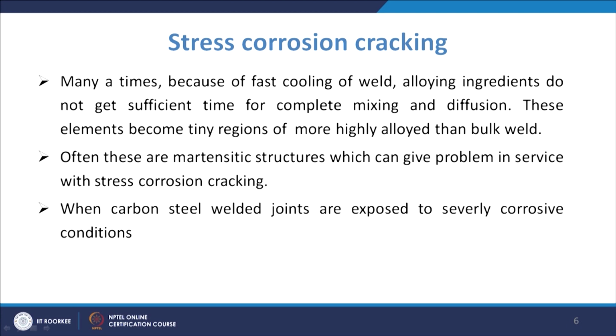So, you will have localized regions with highly alloyed elements. There will be a few regions which have these alloying ingredients in a larger quantity than is found in the bulk weld. Often these regions are martensitic structures, and that will give you problems in service.